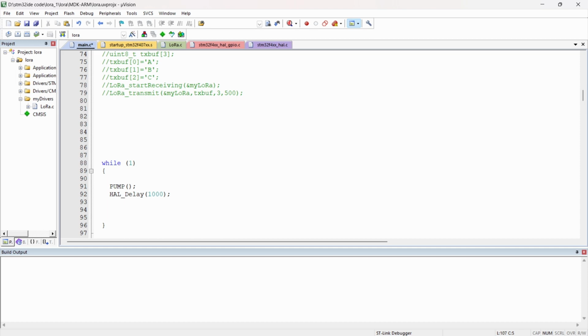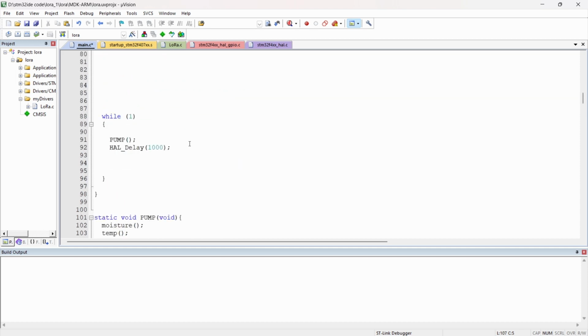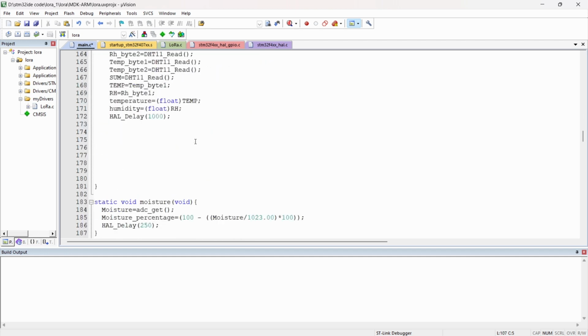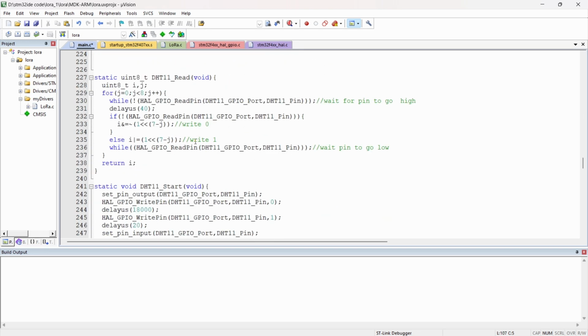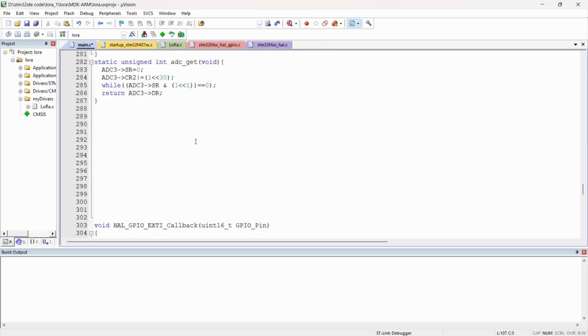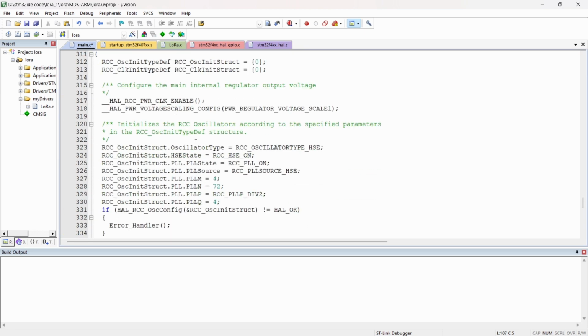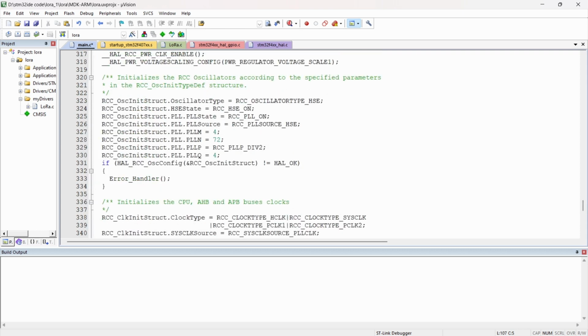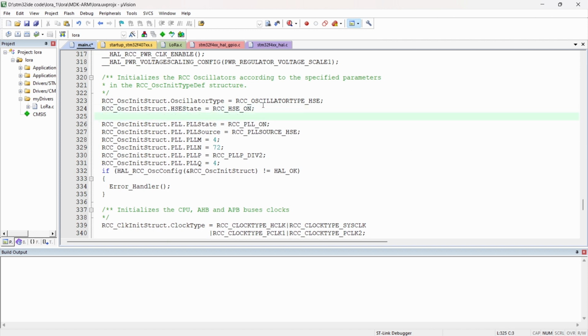What you have to do first is turn on this LSI clock oscillator. Go to the GPIO init function, which we have defined already. We have this here, right? The first thing we have to do is turn on this LSI internal low-speed clock, which operates at low voltage.